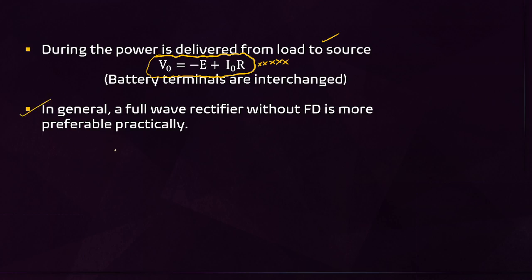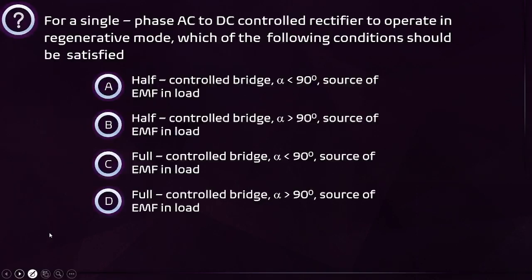In general, a full wave rectifier without a freewheeling diode is more preferable in practice. Why? Because only without a freewheeling diode can it operate in both the motoring mode and the braking mode. This question you have to practice.